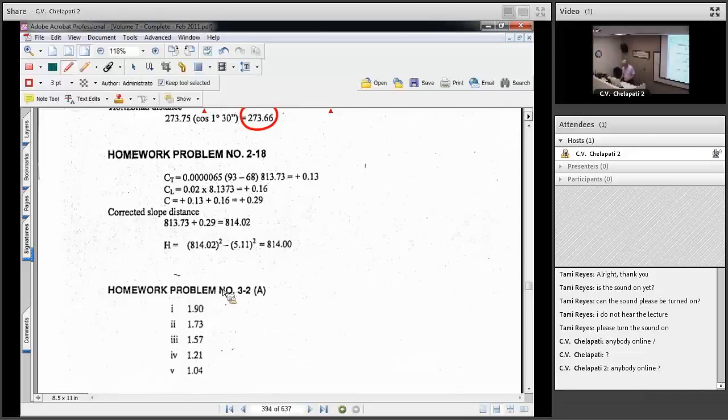So we have three things to correct for. The first, remember, we're always going to do temperature first. So the temperature is plus 1300. That's a significant amount, right? 1300ths of a foot. That's a pretty big correction. But you can see the temperature correction is pretty big there. It's almost 30 degrees, 25 degrees to be exact. And corrected for length, we have the 200ths times 8.1. Where did this number come from here, this 8.1?